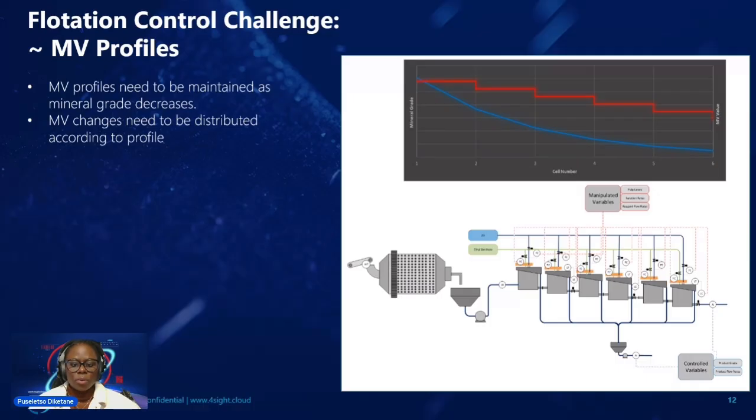Now, in traditional operations on our plants, what we typically see is that this profile is the responsibility of the operator to maintain. But what we also often experience is that this particular measure can be overlooked at times, which then leads to excessive recovery of your waste material within your final product streams, which is essentially not what we are aiming for within our operations in the flotation space, because you want to continuously maintain the right quality of your final product and have all of your waste materials reporting to the waste section.